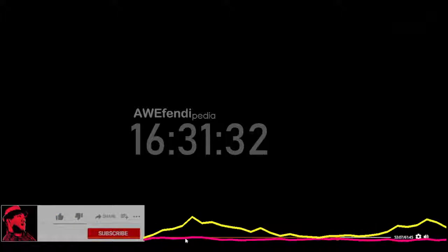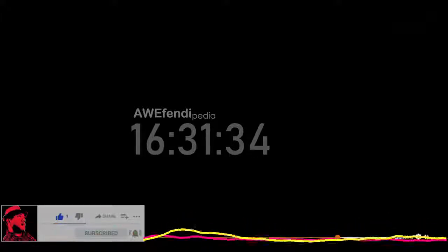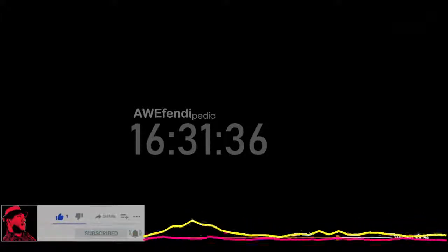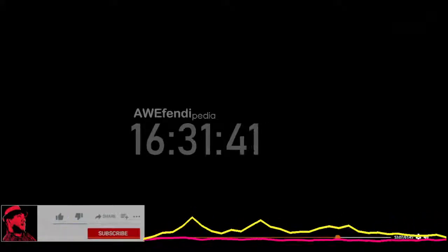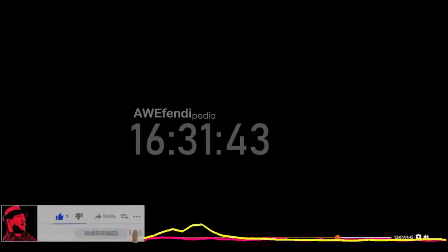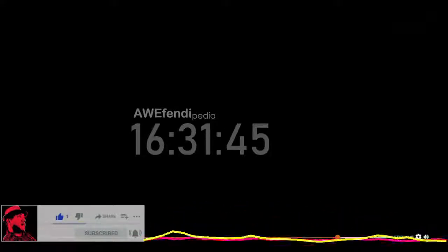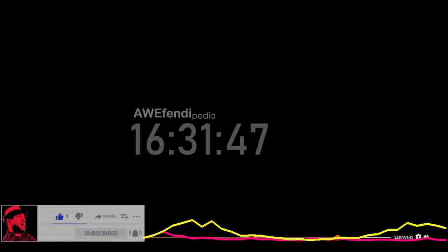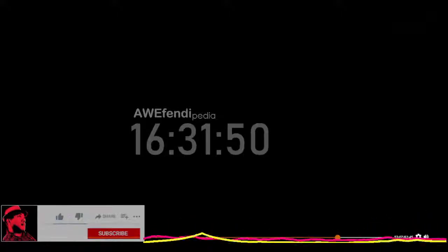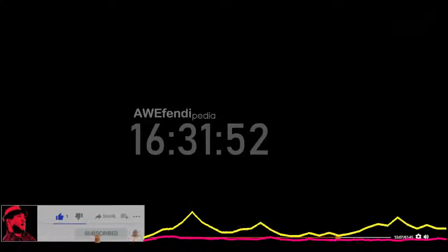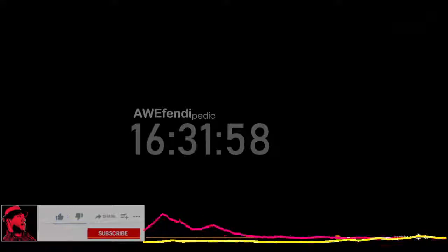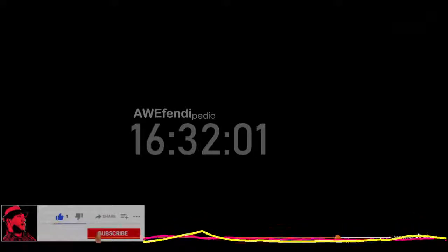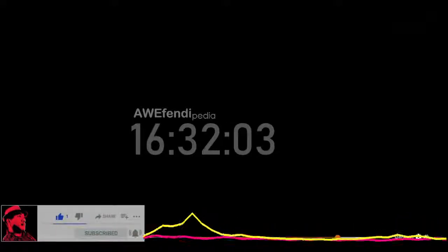I want to go ahead and create a terrain file out of this, a separate DGN that contains this terrain. And to do that, we're going to go to the File menu. We're just going to create a new DGN from a 3D seed again. We're going to hit the New button up here and create our 3D seed. Should already be selected down here. We're going to create a new DGN to house this terrain. I'm going to call it terrain and hit Save. And it's going to create that blank DGN file for me.